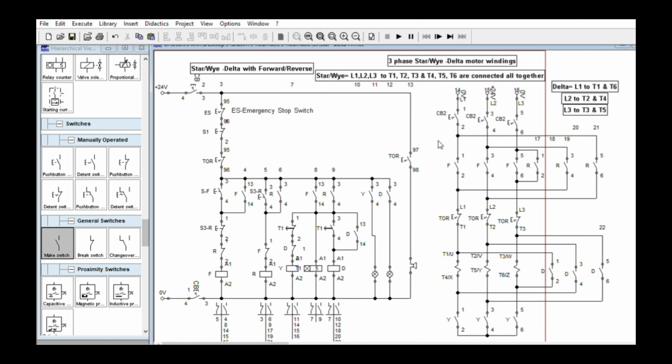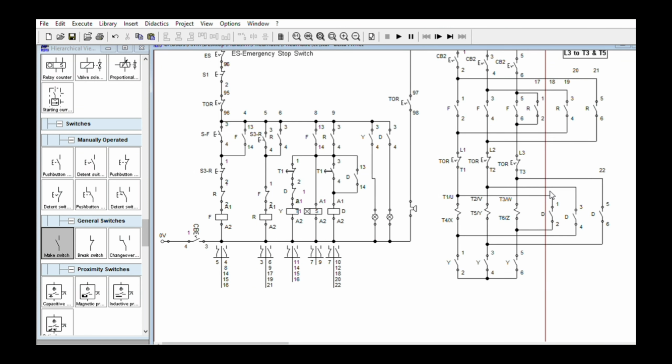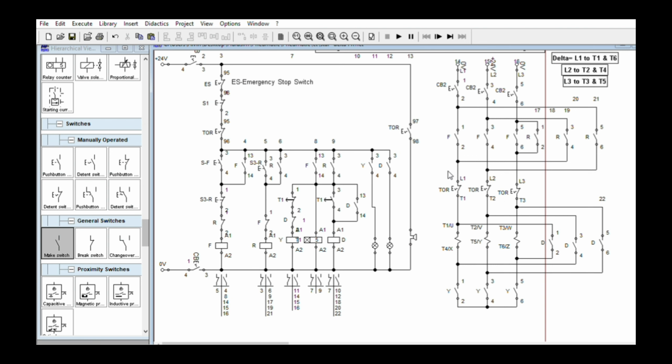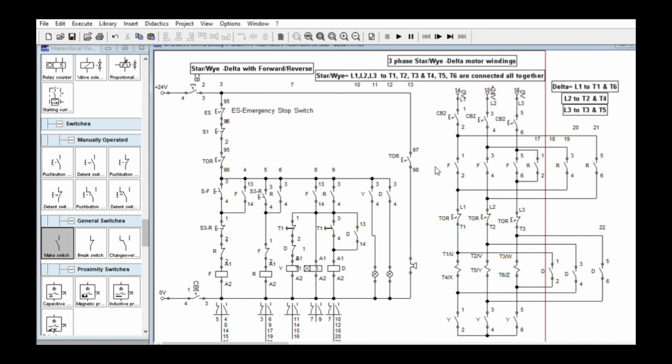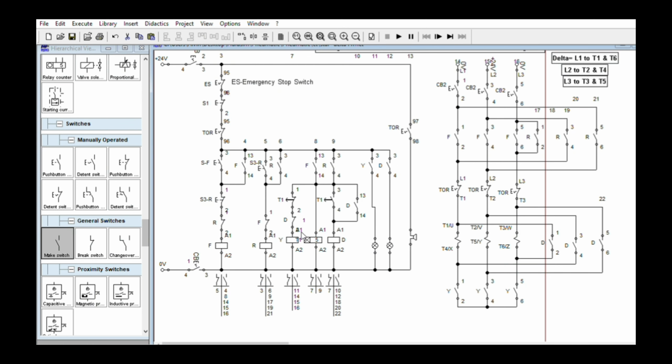You assemble this one all together and make a line there and go it here. Jumper. And this one no more overload relay because we are using only one motor. Always connect this way so that the current will always pass to the overload relay. And this is it about star delta with forward reverse. And the transition is automatic from star to delta.